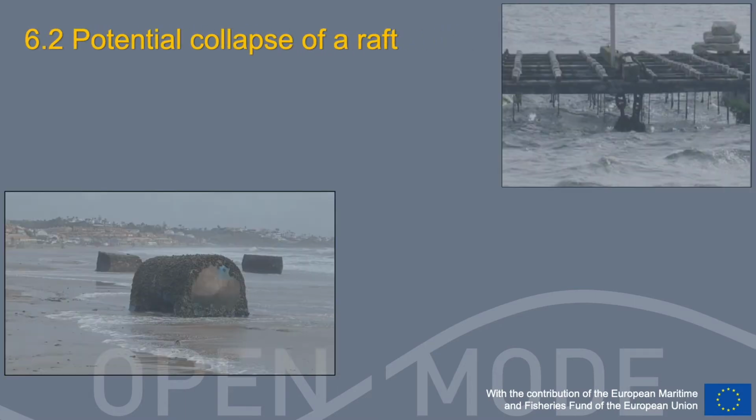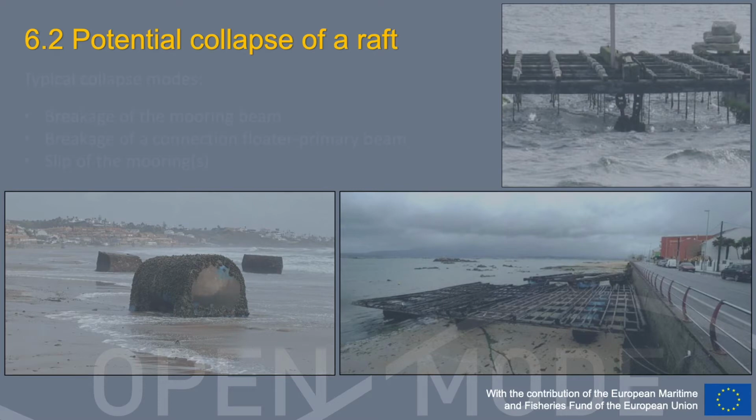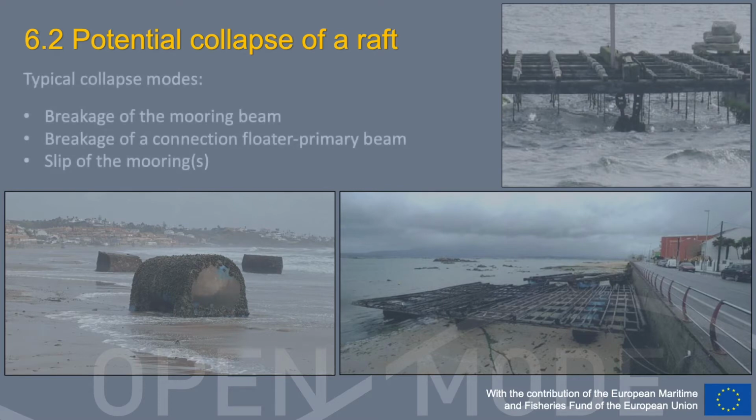Well, the second point I would like to mention regarding the safety in a raft is its potential collapse. Most of the experience regarding the collapse of rafts is related with wooden rafts because they represent more than 90% of the rafts. And the most typical collapse or failure modes are here indicated.